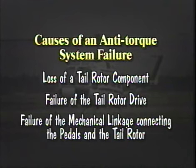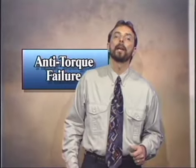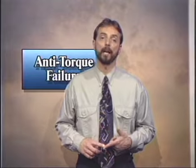An anti-torque system could fail due to a loss of a tail rotor component, failure of the tail rotor drive, or a failure in the mechanical linkage between the pedals and the tail rotor. If the anti-torque system fails while at a hover, you must react quickly.